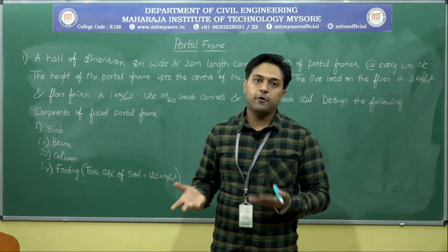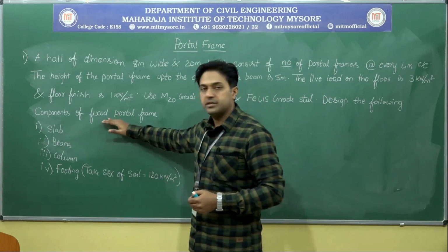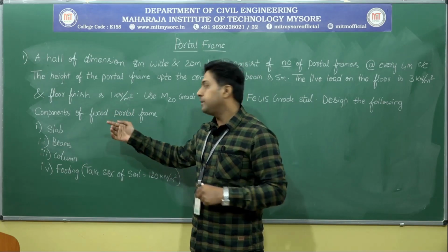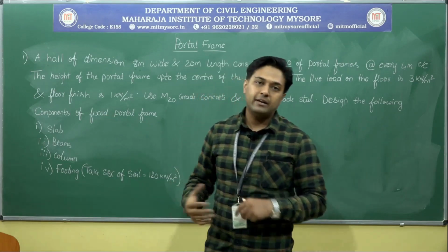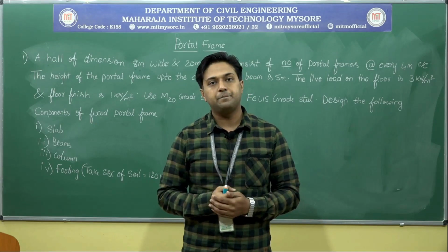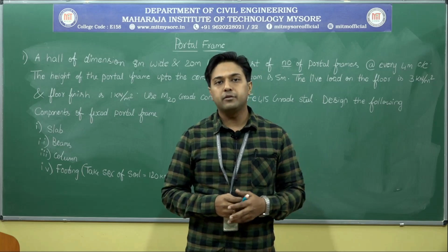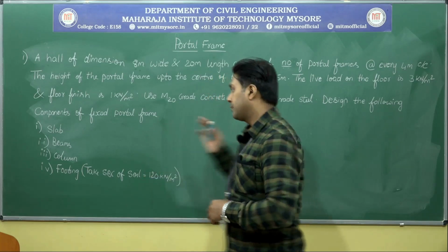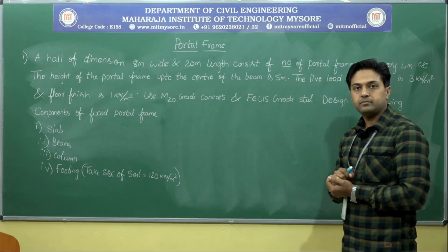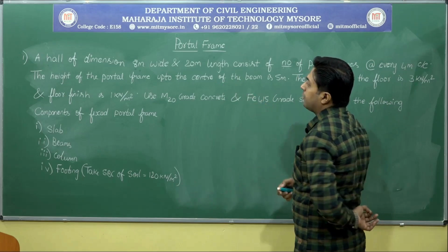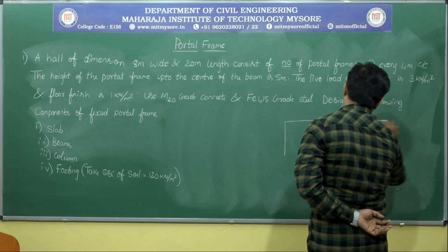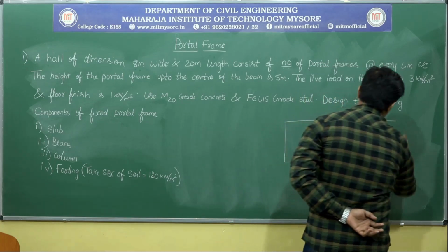In the exam, if they ask for hinged portal frame, please be careful with this. Even though in the question they have mentioned hinged, if by mistake you have done the fixed portal frame, then the value will change. Procedure is same. I will be explaining that a little bit later. Okay. So, now let me enter into the design part. Let me briefly explain what this question is. They are telling a hall of dimension 8 meter wide into 20 meter length.